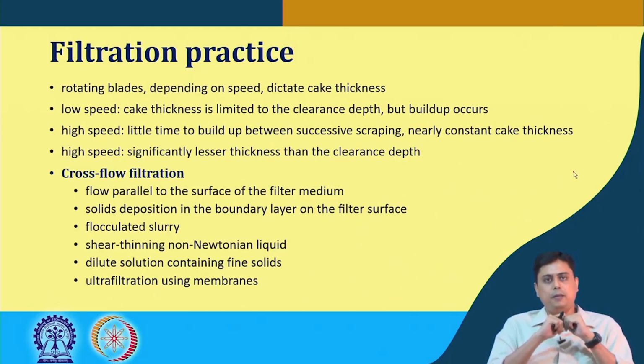So, at high speed we actually have a constant cake thickness with time, and here we achieve a significantly lesser thickness than the clearance depth also, because once this is rotating at a very high speed, near the blade there are wakes formed in the suspension, local turbulence.